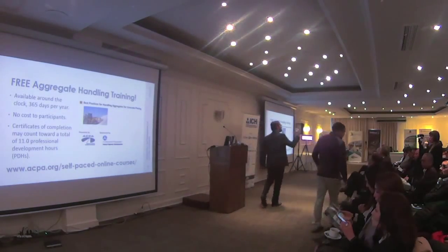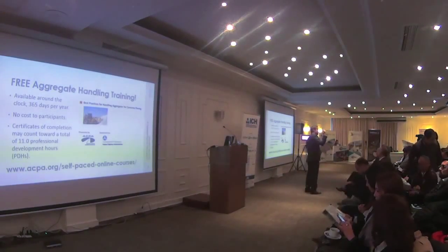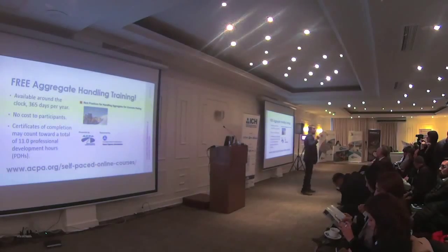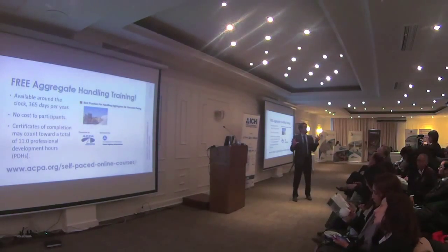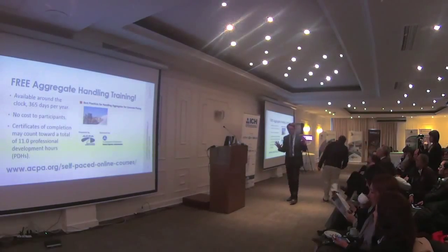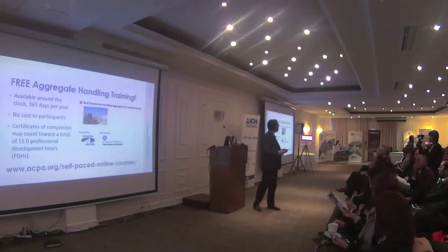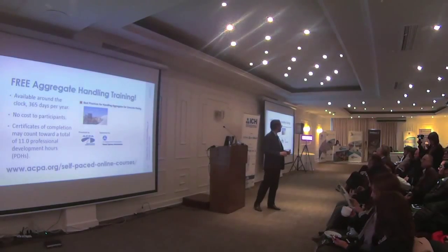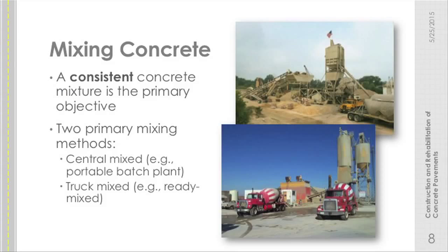We have to make sure there's no clay inside the aggregate. We have to make sure they're as clean as possible, that they're as uniform as far as the gradation goes, every little detail. Again, we're so far along in this process of the very expensive task of building roads that to have things go wrong at this point undermines the entire process. So these people that are doing this position need their own training.